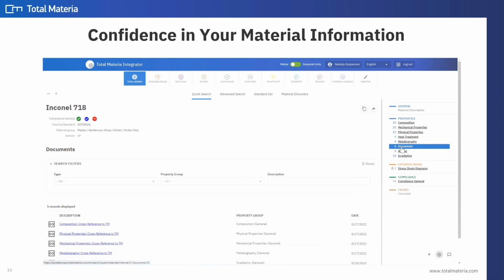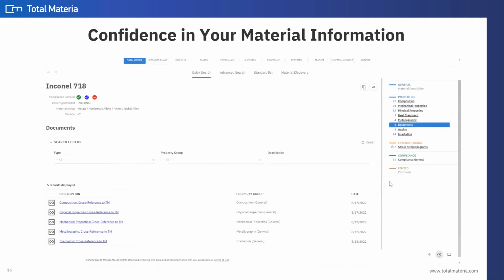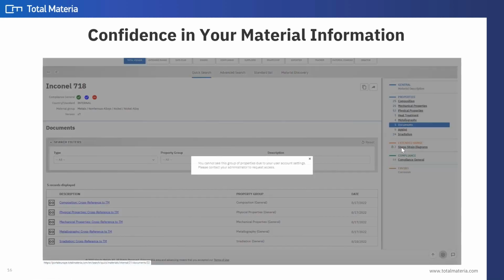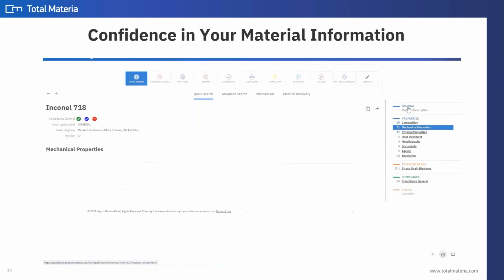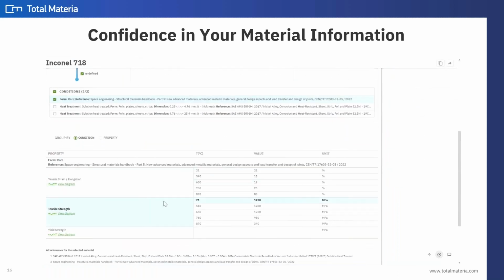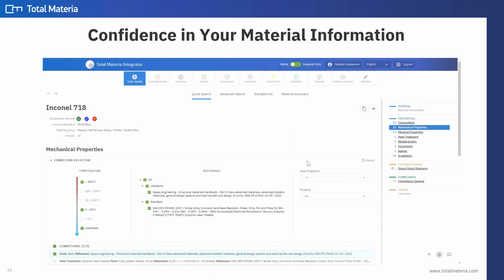You can see in Inconel 718, actually we copied it into our database and we are adding some different documents for that. Aging information, validation testing, or whatever test you just made for this material, you can add it. You can say that some users can see only mechanical properties, some users can only see the chemical composition of the material, or CAE engineers can only see the stress strain curves of the material, or whatever you want to set as a user management system.